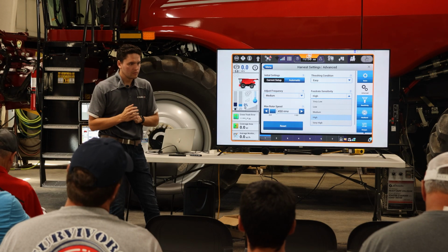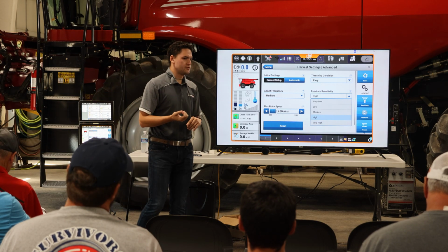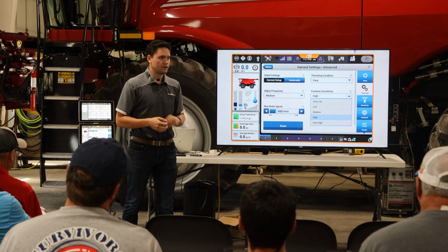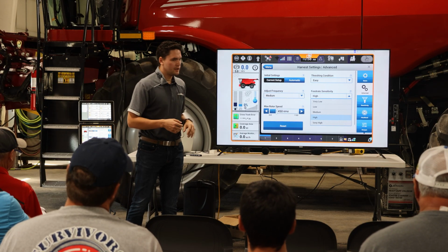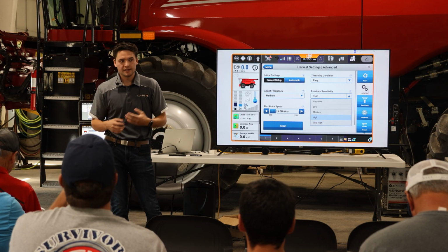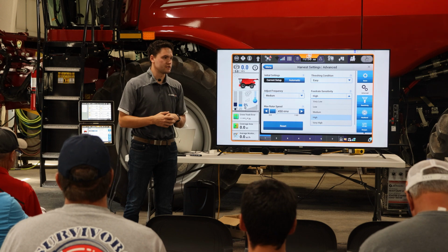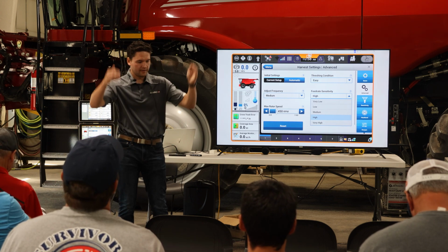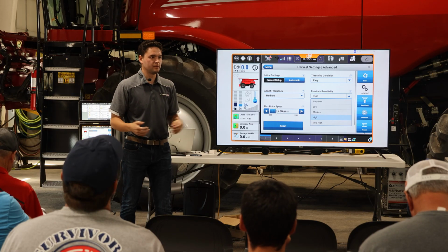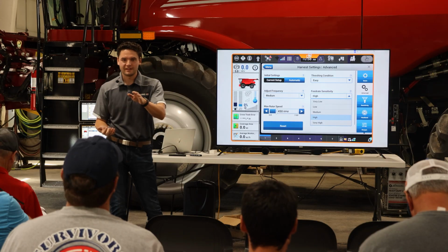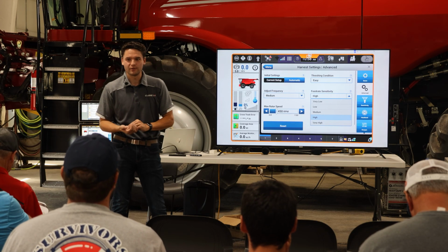You don't want to go too low, because if you go too low, then we have things like slug prevention that might not be there. If our feed rate is calibrated correctly and we have the settings correct, it should prevent us from having a slug. Unless, of course, we go from 5 miles an hour and then immediately hit this extremely green patch. That's a little bit hard to compensate for. Yes, that might justify taking over manual control on that one.